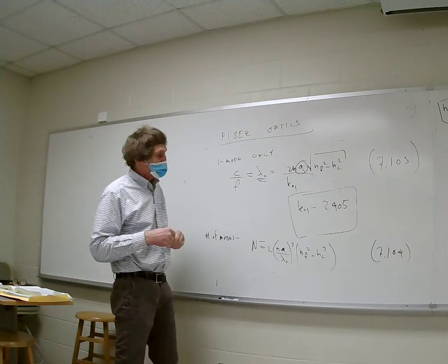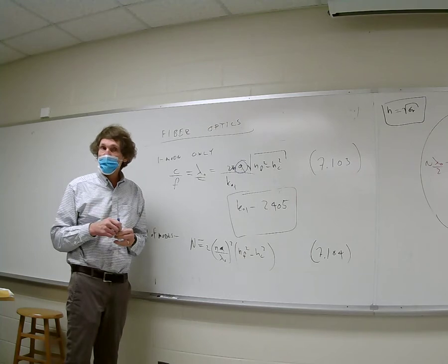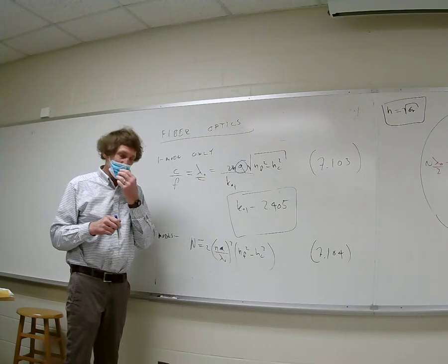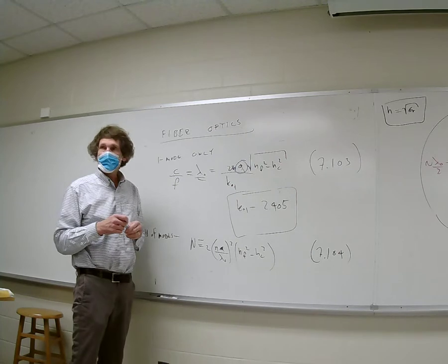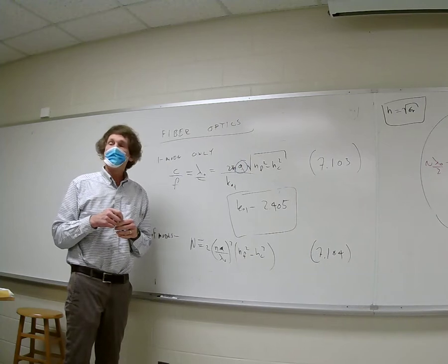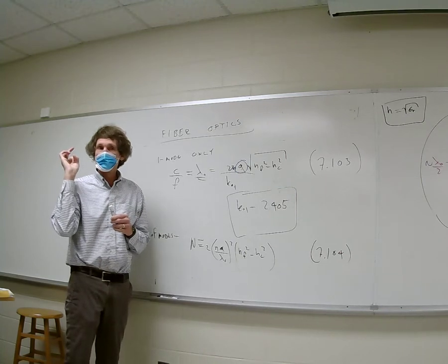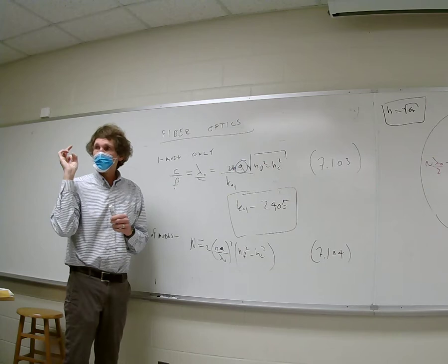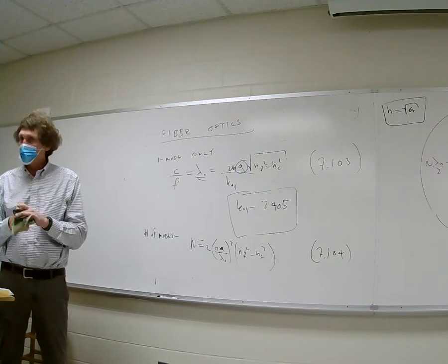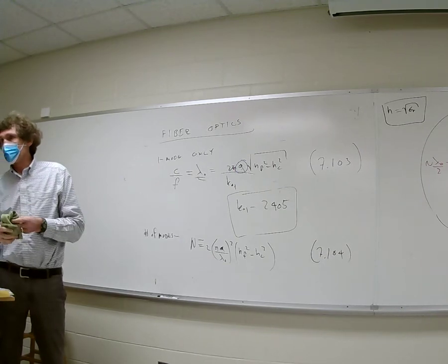I'm going to tell you one other thing about this Bessel function stuff. In the waveguides in this class, we don't cover cylindrical. If it was up to me, we would. Cylindrical waveguides are used, they are. But primarily, most of the stuff you're going to be dealing with is microwave dishes, and if you have a dish antenna on your roof or anything like that, it's a rectangular piece that fits in there, and it feeds usually from a coax. Usually rectangular guides are the ones you need to know about. There are reasons to use cylindrical waveguides, but that's a little outside the realm of what we're going to deal with here. It's more graduate material. I can tell you about it if you're interested. It's easy for you to figure that out once you've been introduced to rectangular.